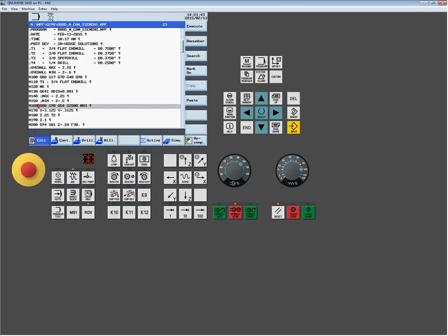So you want to be careful when you're posting programs: how do I handle this? Well, you've got a couple different ways to handle this. Certainly, probably the most common way when dealing with programs where they want to have some ability of adjusting an offset out of the machine, it's called outputting from the CAM side. It's still going to output a G41 or a G42. I can see my G41 is here. We always hide it on me, right there. So there's your G41. This is what's turning on the comp. If that wasn't there, this issue wouldn't occur.